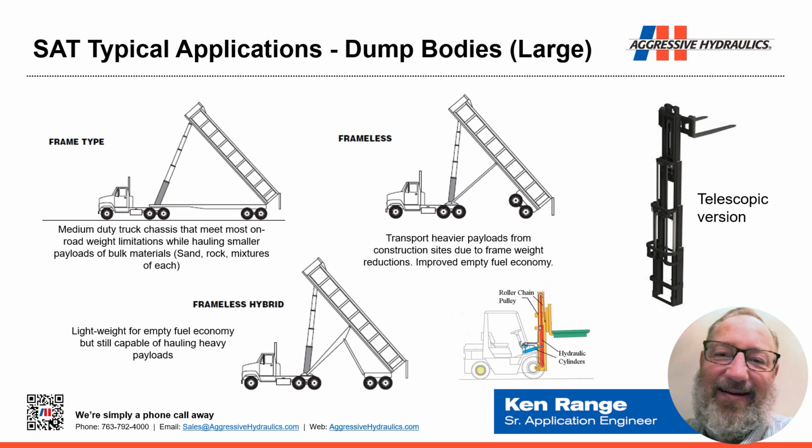In addition, we have fork trucks that are shown on the right side of this image. In a basic fork truck, there's a cylinder arrangement with a pulley and a chain that causes the lift forks to raise and lower. In a multi-stage or telescopic fork truck, one that you might see at a port offloading containers or something like that, or lifting pallets onto a very high racking location in some stockroom, the telescopic cylinder moves multiple stages on the frame of the fork truck, causing the forks to raise a significant distance. And that distance can be two stories tall. So that telescopic cylinder might have 3, 4, or 5 stages.